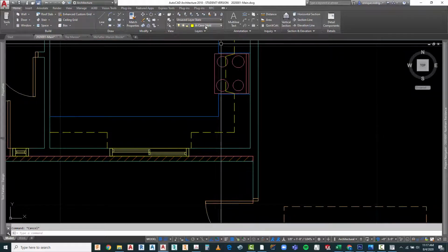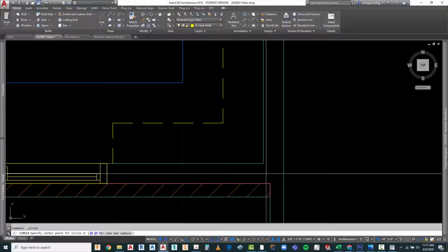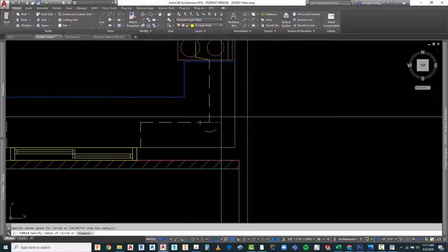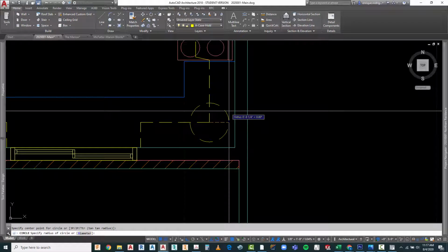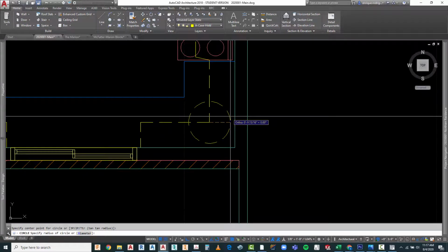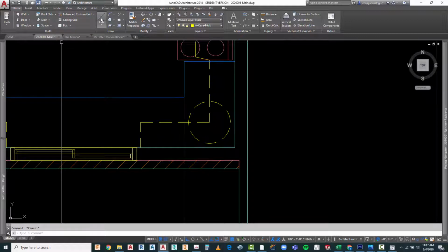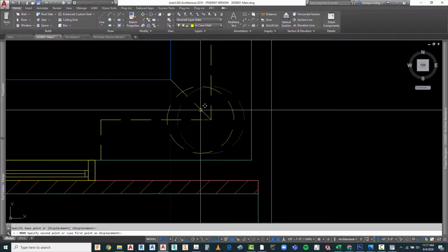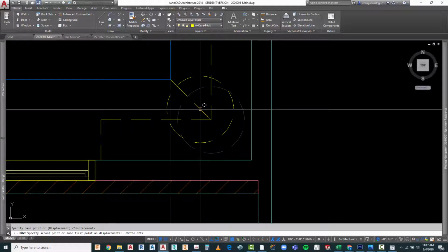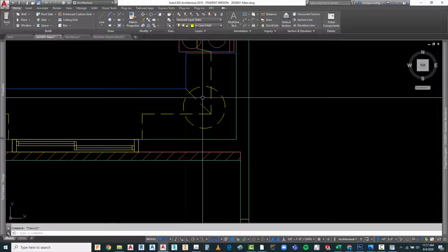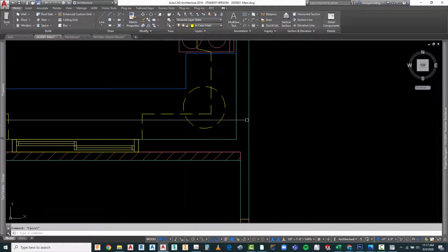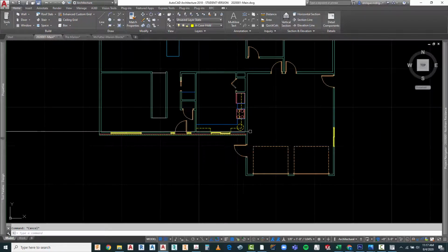I'm going to stay with A case hidden. It looks like we've got what's called a Lazy Susan, which is a storage item right here in the corner here. So I can just do it from here, and I'm just going to draw an item to about there. And I'll bring it out toward the edge just a little bit. Using a guideline, I'm going to move it from here, take my ortho off, and bring it a little bit closer to the edge like that. And then I can delete this item. I think that's looking pretty good so far.